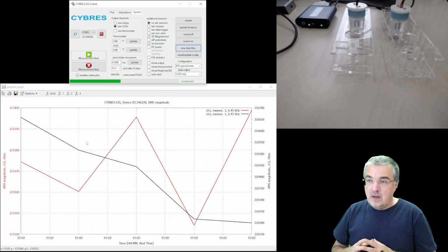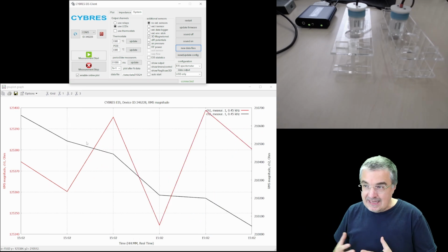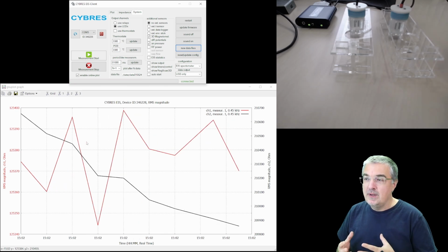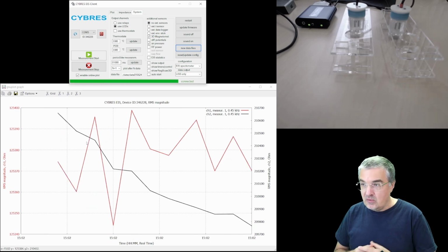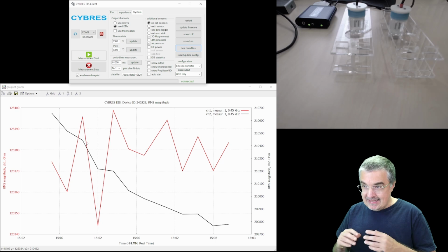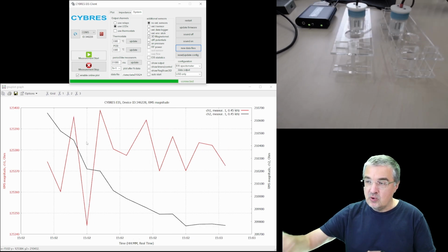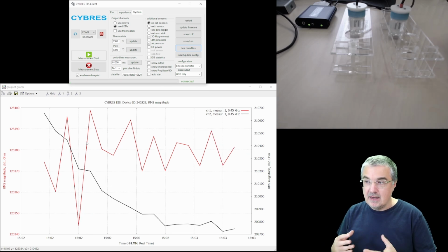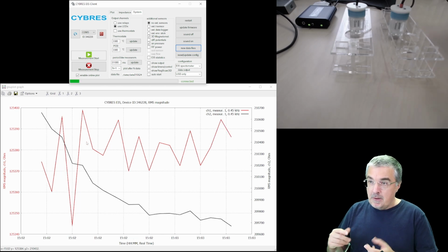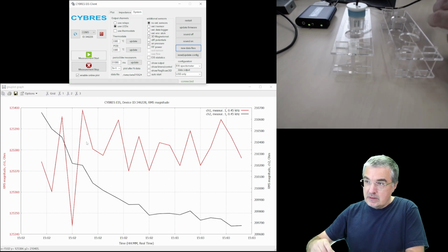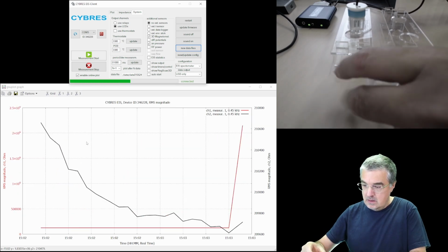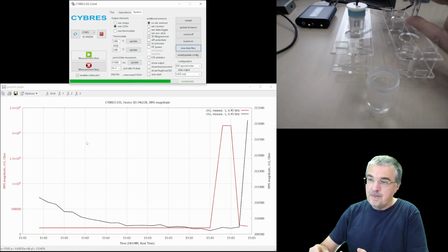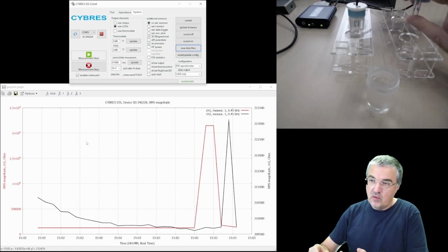Explanation again of what we will see here: my body capacitance has some virtual ground, because here in the room there is a lot of electric field, magnetic field, 220 volt wires, and the system is directly connected to USB. So in this setup I now have the issue of the ground loop that I discussed and demonstrated before. Now I unscrew this, and I touch, so I put my body resistance, and you see immediately a reaction of channel 2.